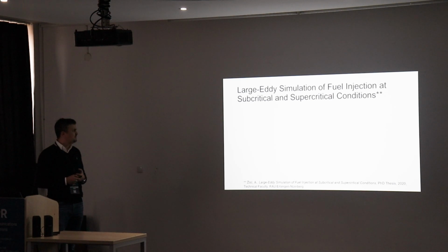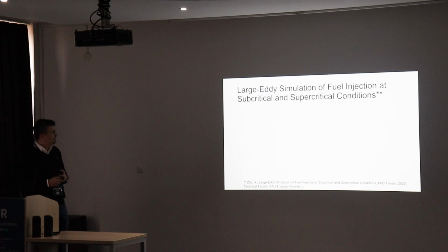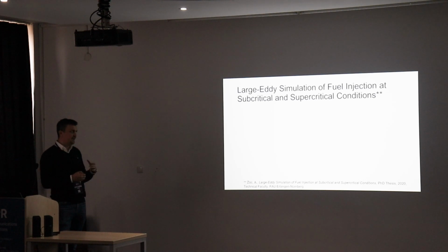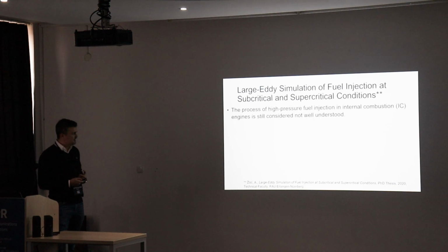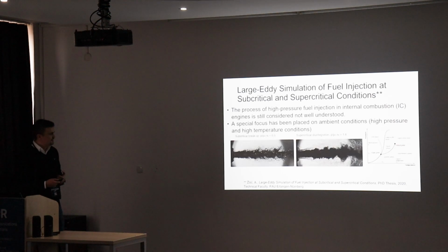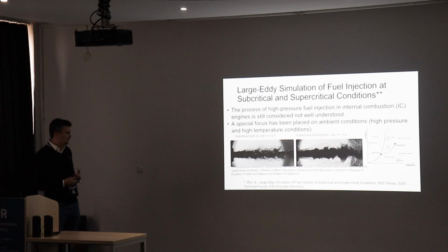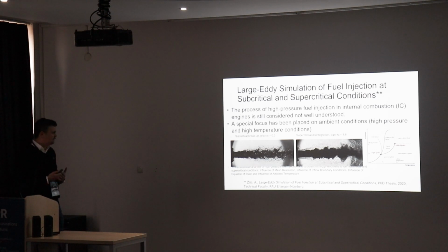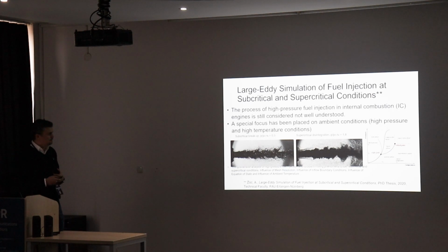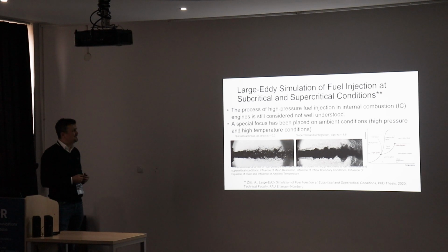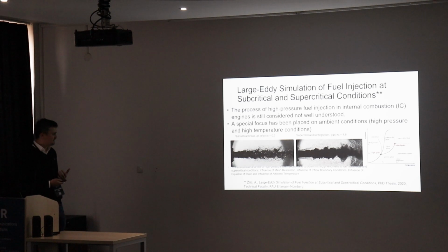This is actually a topic from my PhD research at the University of Erlangen. Large eddy simulations of fuel injection at subcritical and supercritical conditions, again with the CFD approach, but a different application. This is an IC engine application, where I made a really comprehensive analysis of fuel injection for, for example, different ambient conditions in the chamber or engine, different inflow conditions, different equations of state. And as I said, it's again CFD, but now with a different approach for describing turbulent flows. Now I used the large eddy simulations approach.